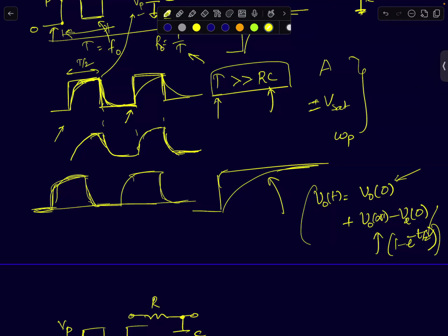So in such systems, when you look at the bit streams, when you transmit these digital bits into those wires, you will see some kind of waveforms like this. It will be, in fact, much more attenuated versions. You will not even see such sharp edges. You will see some waveforms that look like this. What I'm trying to say is that if you understood first order systems, those waveforms should make sense to you. What's actually happening in the system? If the waveforms look like this, wherein the steady state value is attained within a single period, then you know that